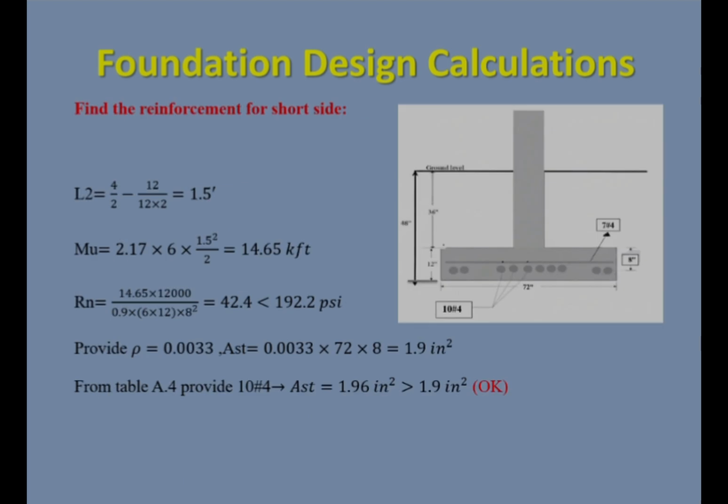So we do the same for the reinforcement alongside the y-axis, and we can see that 10 number 4 is the reinforcement that we are going to put in the foundation alongside the x-axis.